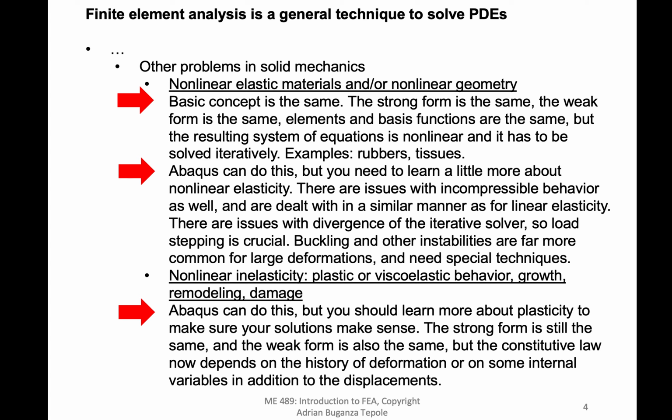There are some issues when you are doing large deformations and nonlinear materials, which is that there are instabilities. Again, you have patterns of the deformation that are, I guess, not nice, smooth, and incremental. Probably you've heard about, I think you did this in the 323 class, Euler buckling. So buckling is one type of deformation that can occur where you are applying a load and then there's a region or a level of force at which there is deformation without extra force, and actually the force goes down. So it's easier for the material to deform even while you're not applying any load.